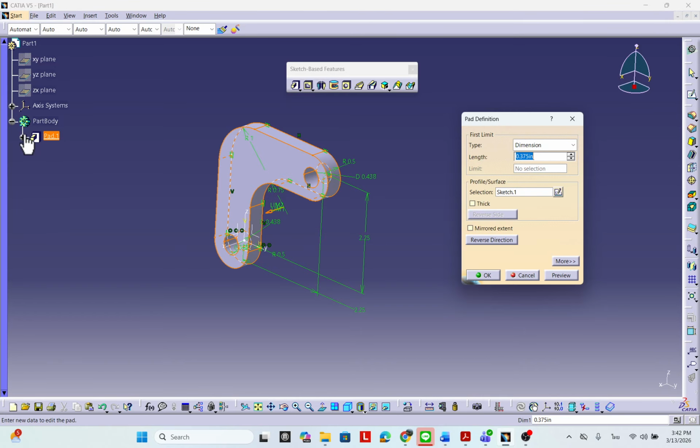The history feature shows which command each feature came from. You can check what steps you have done before. If you need to revise some parameter, you come back, click on the previous command, and go along the tree diagram step by step in its order.